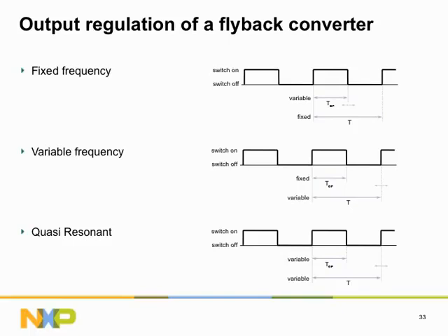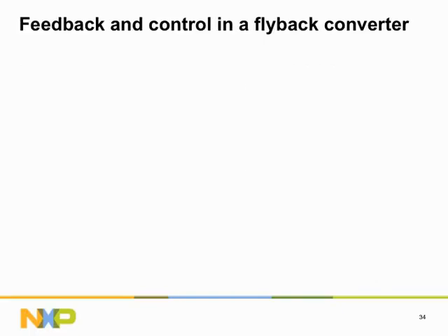It is the task of the SMPS controller IC to drive the switches in the switching network in such a way that the output is regulated in the desired way. Simple controllers will usually have just one operating strategy implemented, and more advanced controllers will change the control strategy dynamically. In order to regulate the output properly, an SMPS controller will need information about the output. Again, we will take the isolated flyback converter as an example.